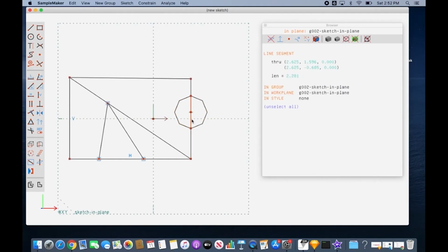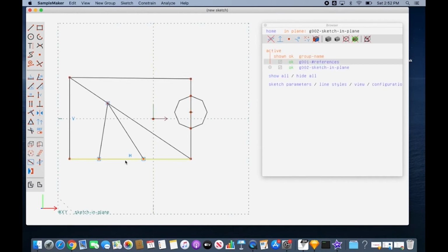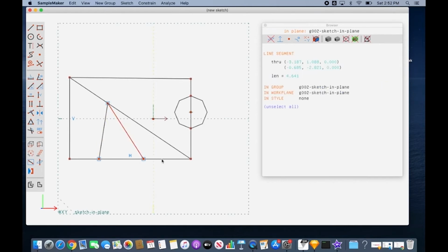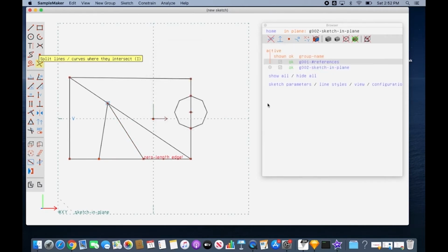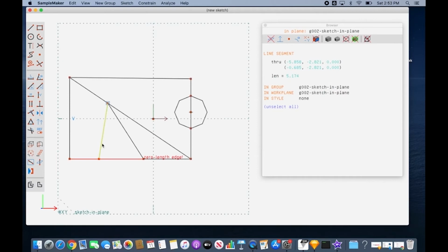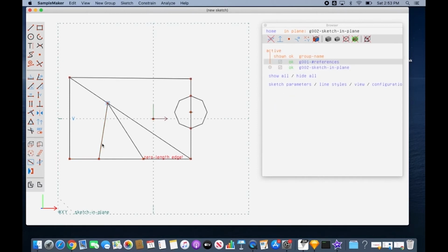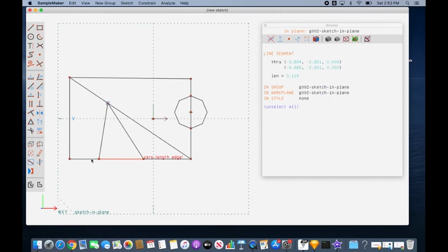If I want to segment down here on the bottom, I'll say, okay, I want to break that, so I'll pick this line and that line. I'll go to the tool and I'll break it. It'll give me this message because I had a constraint there. I'll pick again. Notice I have to do it one more time if I want that middle piece of that middle triangle, and then I'll just hit the hotkey this time, and you can see that I have it segmented into 3 pieces.